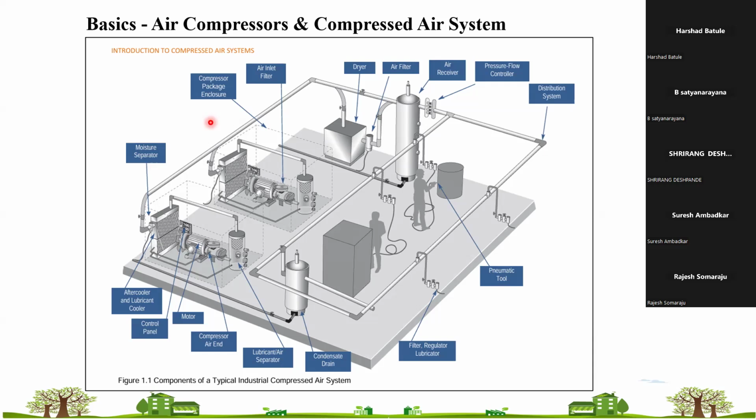During the discussion of free air delivery, we discussed that free air delivery depends on your temperatures. There can be an effect of temperature on your free air delivery. If your ambient temperature is higher than your test conditions or standard operating conditions, you will see that your FAD is on the lower side. So FAD has a correction factor.